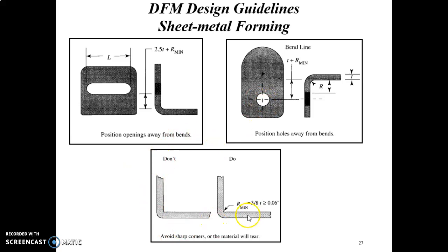Okay, for this one, it is the sharp inside the bend. A sharp inside bend radius is not recommended in sheet metal design because it can cause material flow problems in soft materials and will lead to fracture of the material, resulting in necking or fracture.